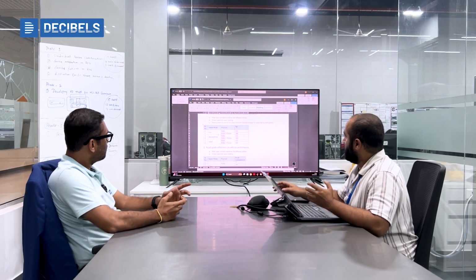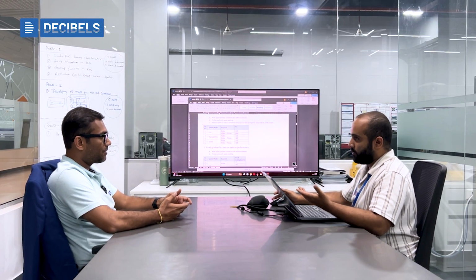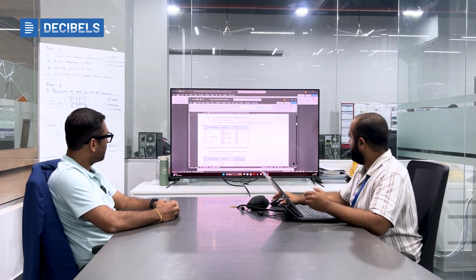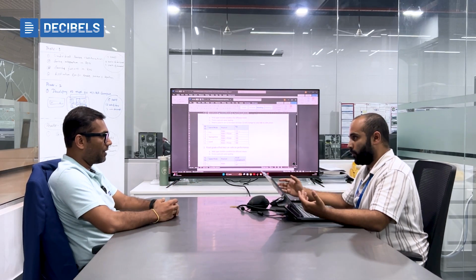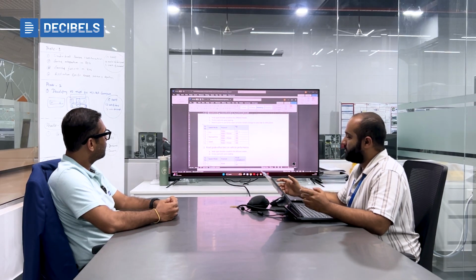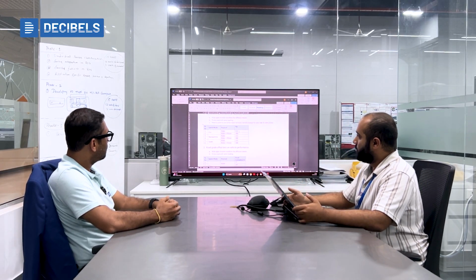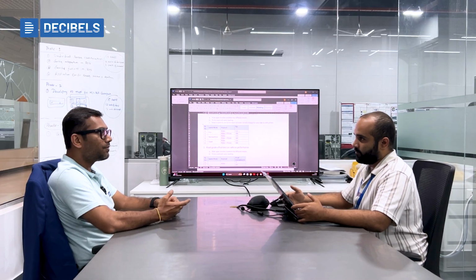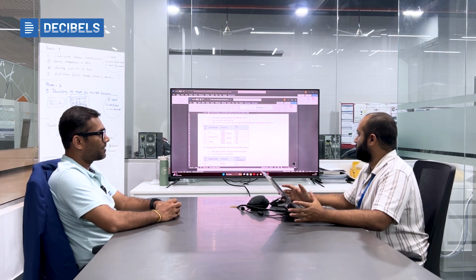If we estimate around 75 kilograms for a person's weight, we consider around 254 kilograms overall vehicle weight, that is the GVW. And for the rider and pillion, we consider around 300 kilograms. So for these conditions also, we can do it on the Dyno itself. No need to put a person on behind, as the same amount of load that would be acting can be simulated.